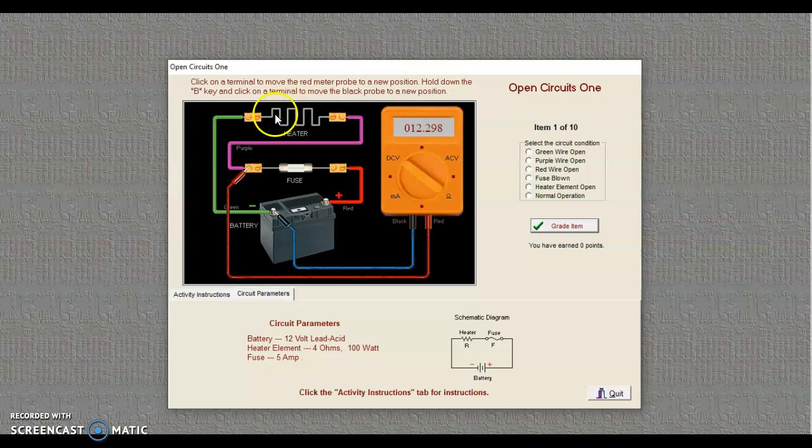And so that has most of the series load voltage, and the fuse in this case is actually intact. The fuse has a very slight amount of resistance, so it will have a small load voltage. This is actually probably a normal circuit operation that we're looking at here. So if I move my probe back to this side, notice it goes up, and in a summative manner, we have the heater element plus the fuse equaling my source voltage here.